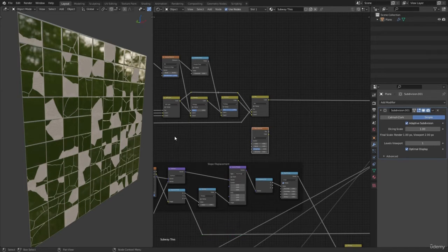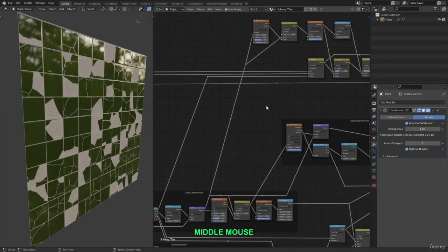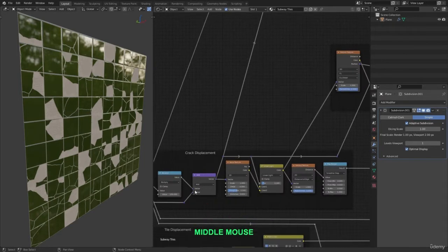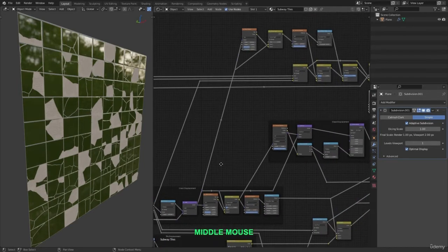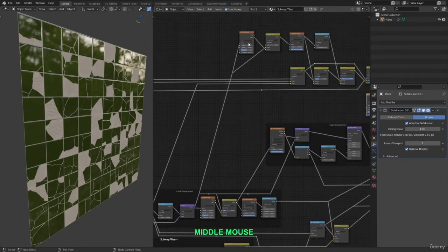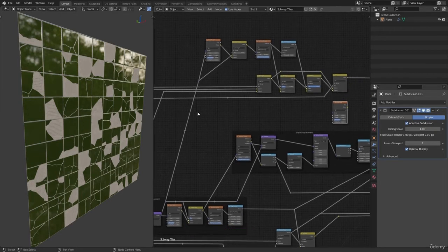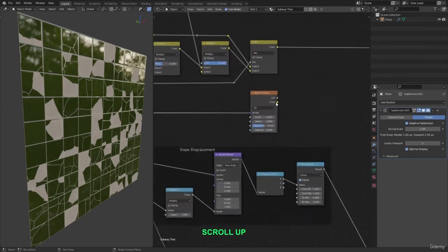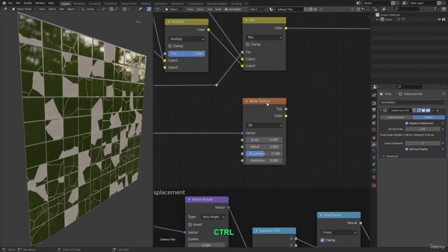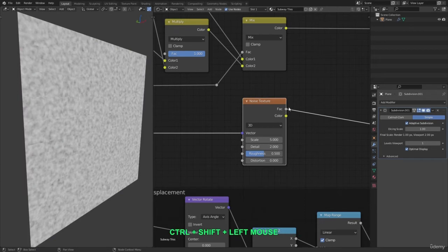And this will need some texture coordinates, so let's grab the main texture coordinates coming up from the add node right here. And it's already going up to the other texture nodes up there. So let's just add a reroute through that line and then stretch it on over. So let me hold Shift and right click and drag through there for a reroute, and then I'll click on that and drag it over to that vector input. And let's hold Control, Shift, and left click on this to preview it.